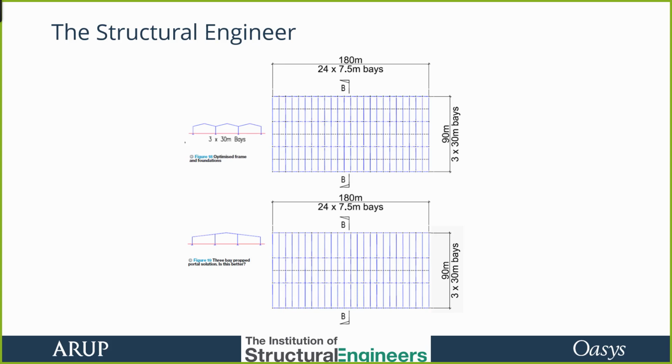And so we decided the optimum is 3 by 30 bays. But then we've now got 2 valleys to deal with. Drainage is difficult on portal frames, on valleys. Expensive siphonic drainage. Maybe it'd be cheaper to use a single ridge. Then the lower pitch, standing seam cladding. Yeah, optimization in the real industry is complex, more than just choosing the right section sizes. And there will be aspects outside your own discipline that you'll need to consider.